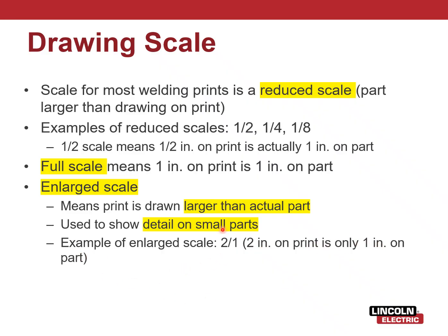And typically in programs, you'll see it labeled not as 1/2 inch, 1/4 inch, or 1/8 inch, or half scale, quarter scale, 8 scale. A lot of times it'll be like a 1:1, 2:1, or a 1:2. Because sometimes you're going from our system, inches and feet, to metric. So kind of like going from the common inches on our side to engineering terms, engineering measurements. So that's what that 1:1, 2:1, or 1:2 ratio denotes in those programs.